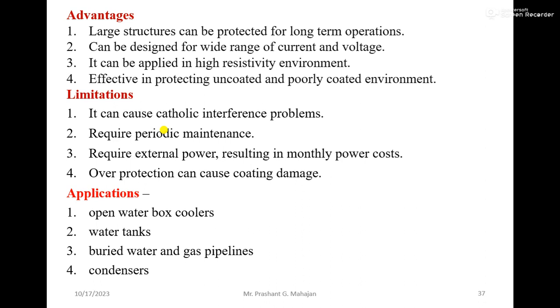Limitations: first, it can cause cathodic interference problems. Second, it requires periodic maintenance. Third, external power is required, resulting in monthly power cost. Overprotection can cause coating damage. Where it can be used: open water box coolers, water tanks, buried water tanks, gas pipelines, and condensers.